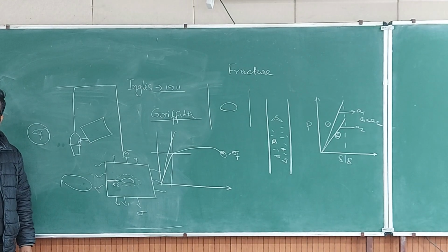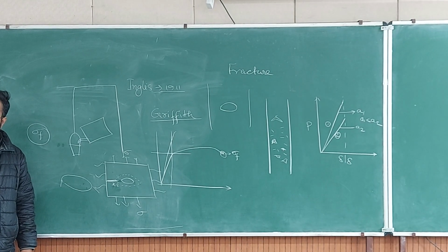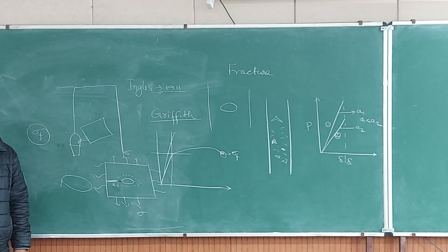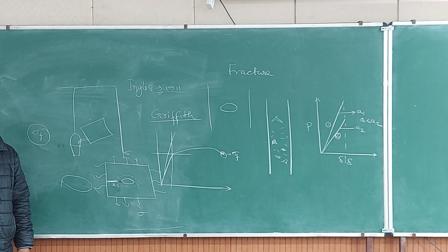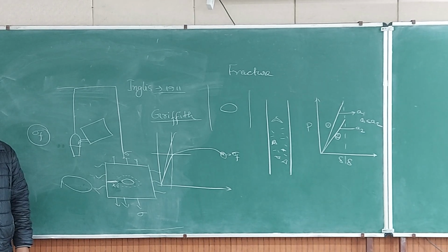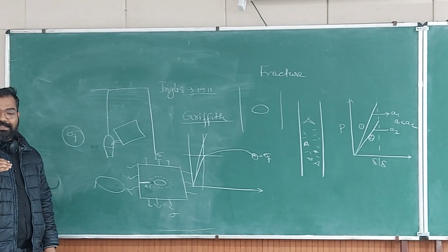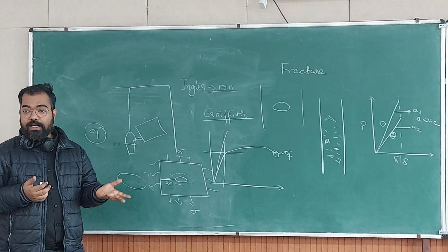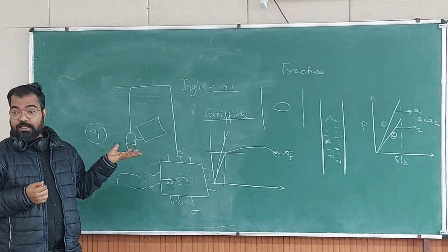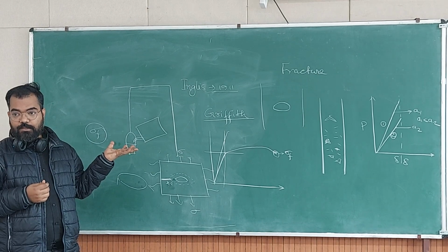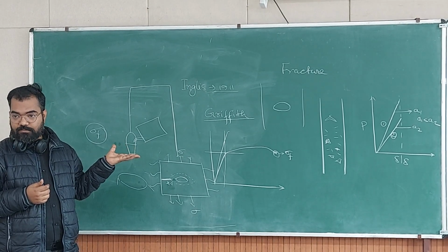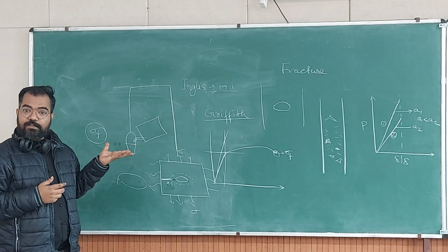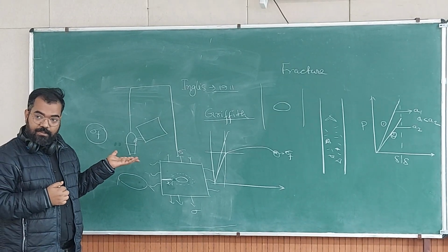And that deformation is going to consume some energy, right? That part is ignored by Griffith. So in terms of Griffith, you are in future. Okay, right? And Griffith is doing his tests on glass, a brittle material. So glass will consume an insignificant amount of energy, so that is not observed in the experiments.